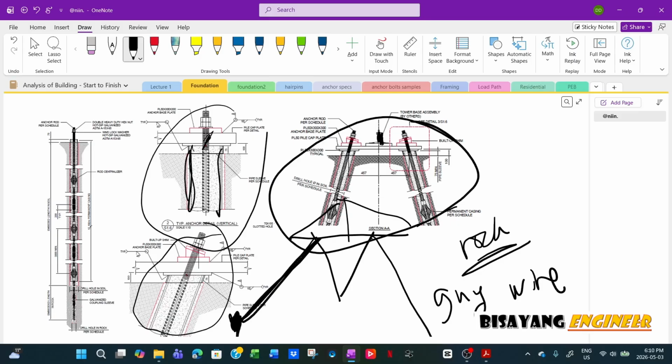The design of the embedment into the rock, and the grout, etc., is done by my colleague, a geotechnical engineer. I have no idea how to design that, but my scope was the structural aspect of it, like the base plate or the cup plate, and then the casing. This is a straight steel casing, and then the anchor, the DYWIDAG anchor.